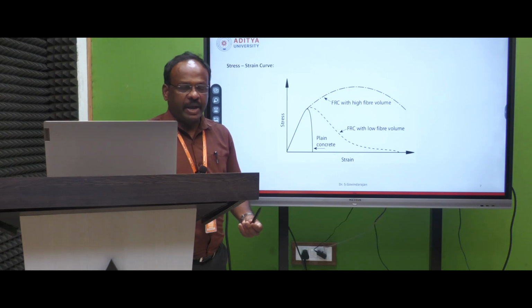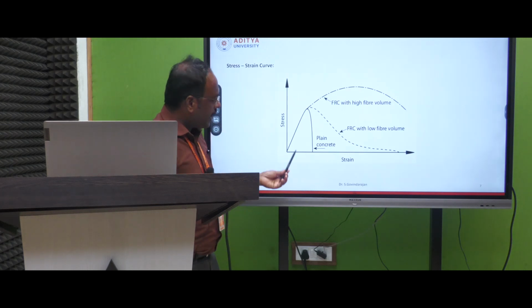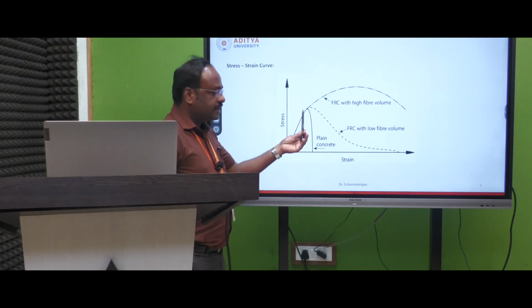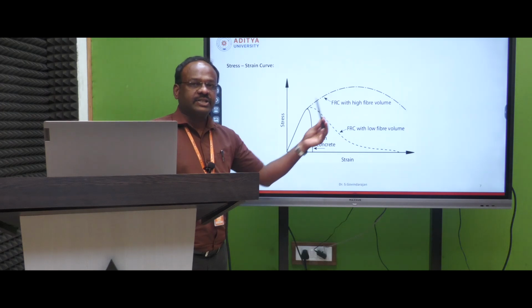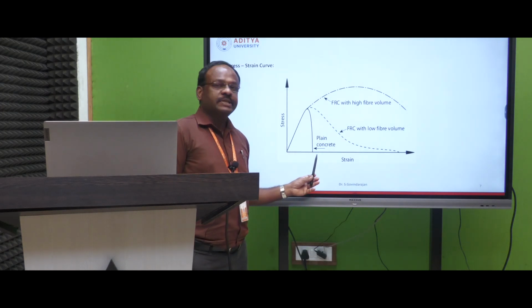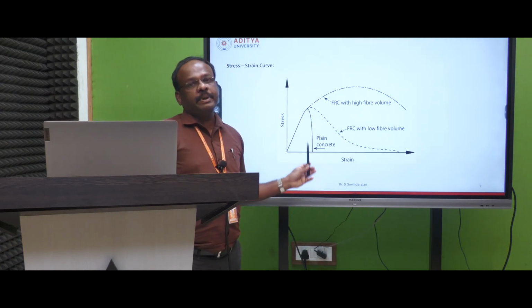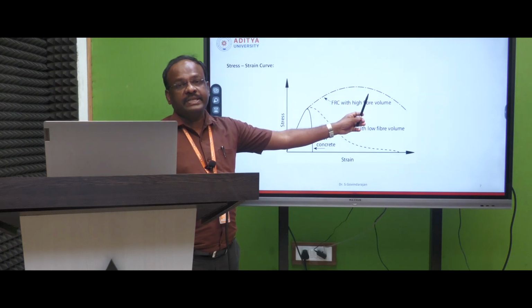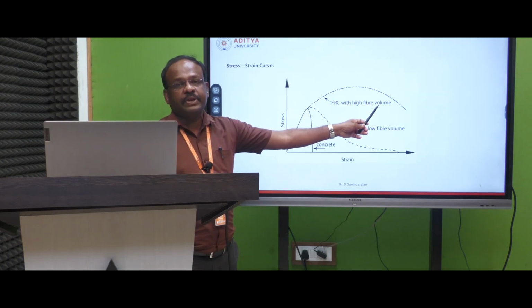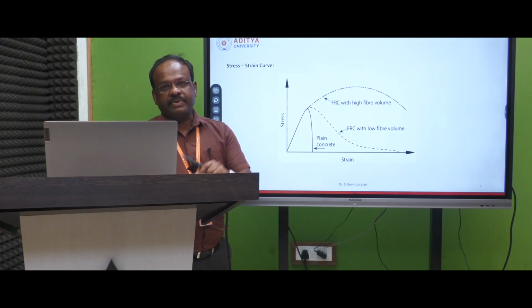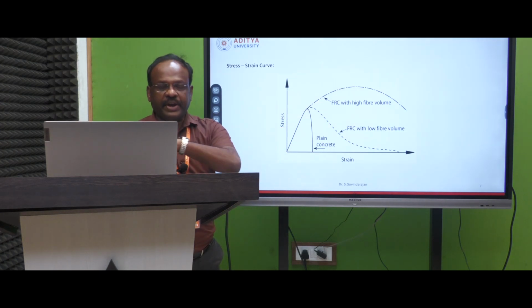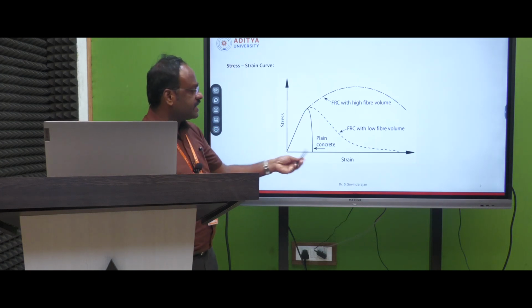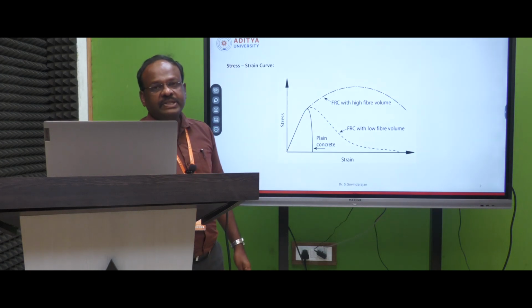But when fiber reinforced concrete is used, up to that extent it is not linear, it is non-linear. When fiber is acting, the graph becomes a non-linear curve. So it does not stop at 0.002, it keeps moving on up to 0.003 to 0.005 also. When fiber is added, the strain value moves on to 0.005 also. So that is the main point of the stress strain curve in fiber reinforced concrete.